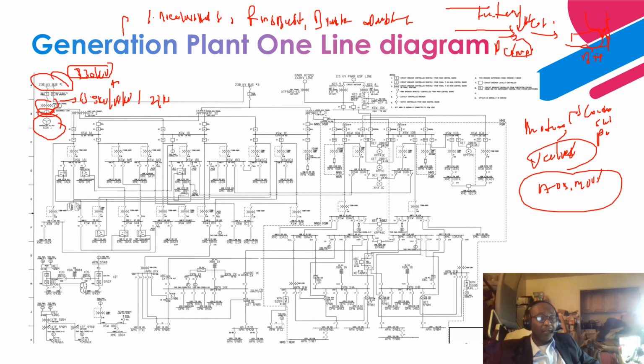So you have a 3-winding transformer, right? You are coming here with 13.8 kV or 18 kV. Then you're stepping it down to, let's say, 4.16 kV as 2 secondary windings, right? Basically, because the goal is basically to utilize one transformer, a 3-winding transformer, to be able to multiply the secondary voltages.